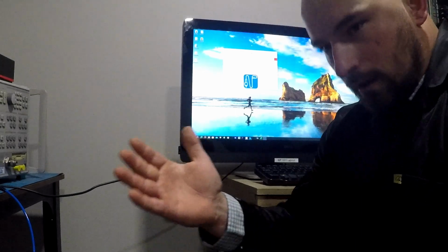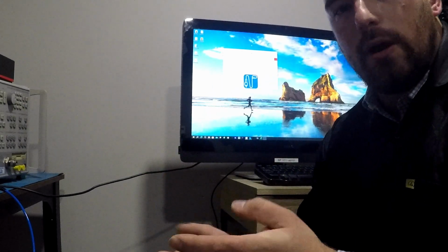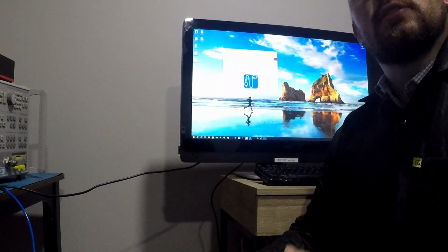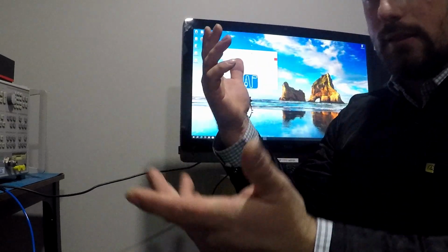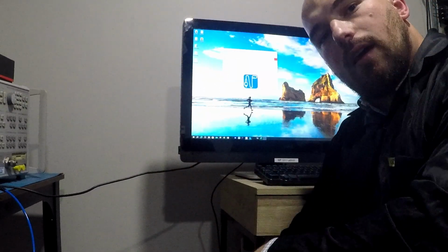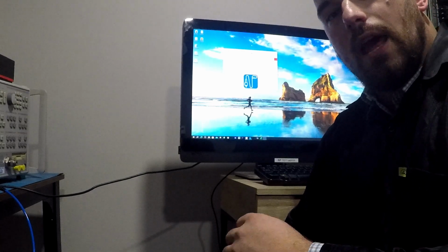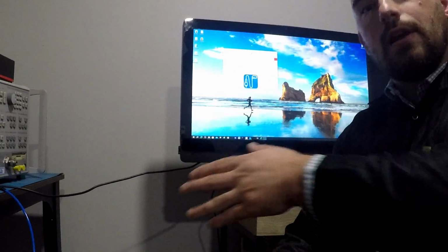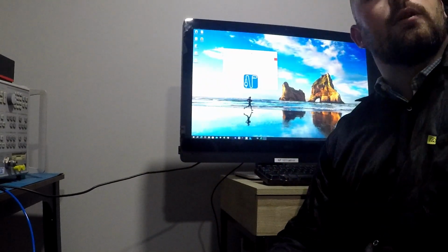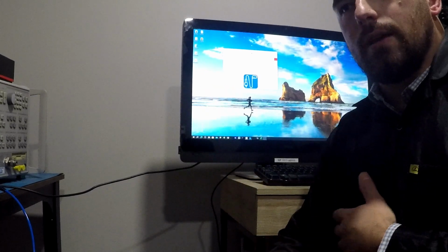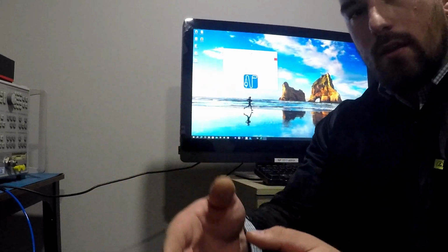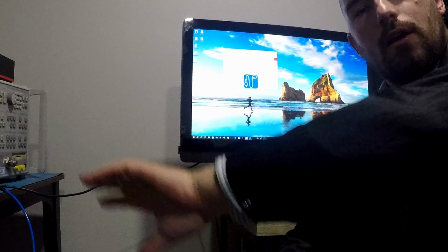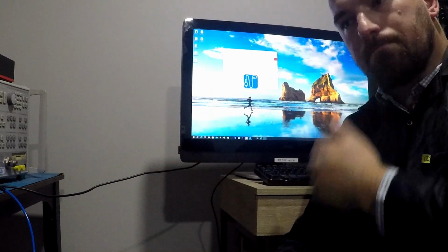Where I see this going, or where I want to take this, is into the beam steering. You design a really good antenna to operate at your desired frequency points, and it can control the ground plane to steer the beam. Now, using some of this AI-based evolutionary algorithm, you can have it beam steer and beam track, so mobile cell phones can always have the main beam, the main lobe steering towards the tower. Vehicle-to-vehicle communications, you can have the signal changing angles so it follows the car in front of you that's going around the curb.